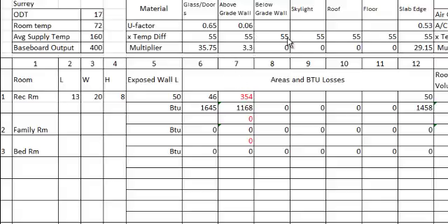Now, the only other item on this list that we need to worry about is the slab edge. When we look up the concrete slab on grade from table 1 on page 1-5, we'll see in the bottom right hand corner there's C, concrete slab on grade, and it shows two different values there, one for 1-inch edge insulation and one for 2-inch edge insulation.